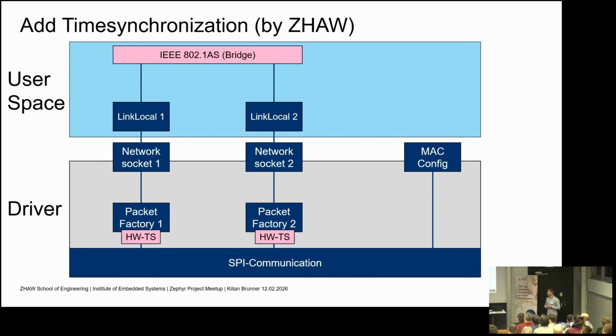The second part is the time synchronization. We at the ZHW are, I would say, experts in time synchronization. We wrote our complete stack in IEEE 802.1AS. Usually this runs on Linux, but we also ported that on small Cortex M4 devices, and it runs easily.